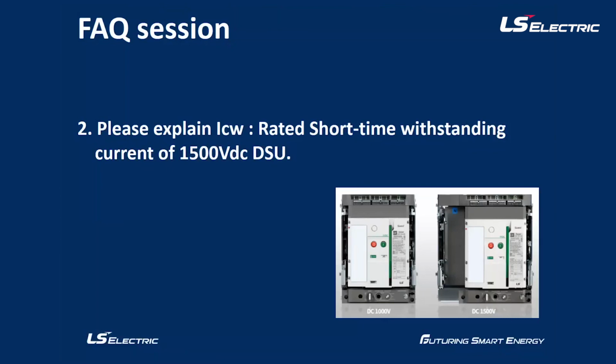So ICW guarantees that the system can continuously withstand a short circuit current. That's why ICW is a very important issue. So actually, we do provide our system with 100 kA for 1 second, but as you can see, ESS systems and PV systems need a shorter ICW time.